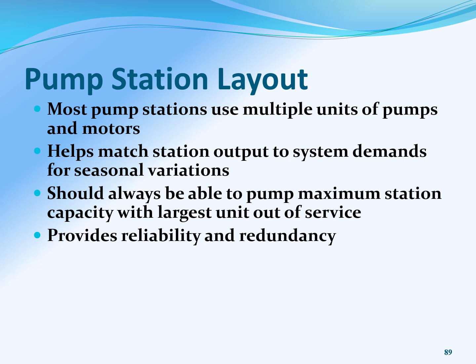But the ultimate goal is to be able to meet the demands of the system, depending on the season. So you want to be able to provide water at its maximum, but then also have your pumps be able to provide water at a minimum. And then you should always be able to provide that even when one of these units is out of service.